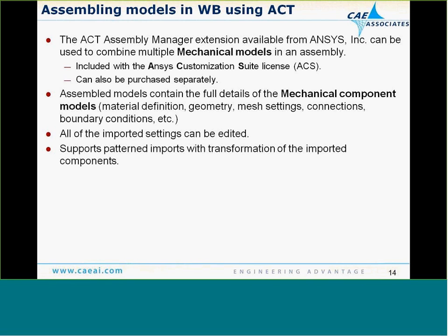Now, the advantage to this ACT Assembly Manager is that you're assembling models with the full details of the source mechanical component. So everything that was used to define that source component is included when you assemble this in the Workbench environment. And those would be things like the material assignment, the geometry, the mesh settings, connections. All of those imported settings, the mesh settings, for instance, can all be edited. They're live. They're not fixed or disabled in any way. So it's almost as if you're taking this model that was created by someone else in another Workbench project and bringing it in as if it was your own inside of your current assembly.